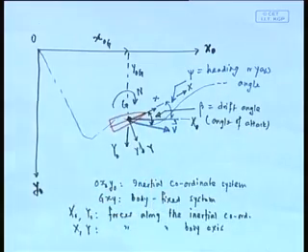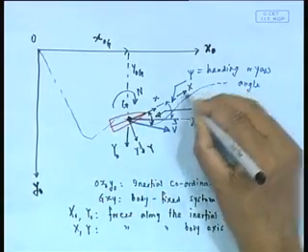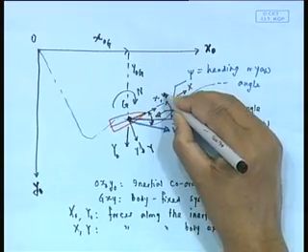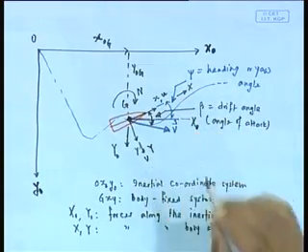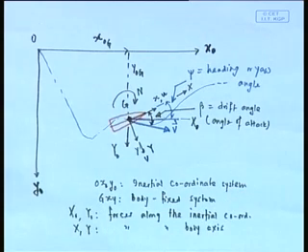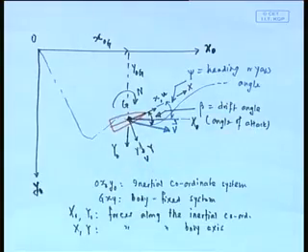But I want the instantaneous velocity along this line, which I call u, and this is going to be small v. When you are on a ship you only see the velocity along its own x axis and how much it is swaying. Sway is basically v, how much it is swaying with respect to itself. So here comes the question, which we are going to do probably next class.